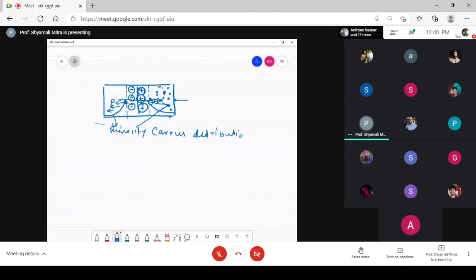Kintu, now the problem with the diode is that as these minority carriers are lost in recombination, we actually don't have anything to harness this property. Harness this property means we don't have any other terminal where we can actually collect these minority carriers to eventually produce some sort of other nature, that is the amplifying conditions, or something like RC couplings. So, did you understand this problem with the diode? They are just lost in recombination.